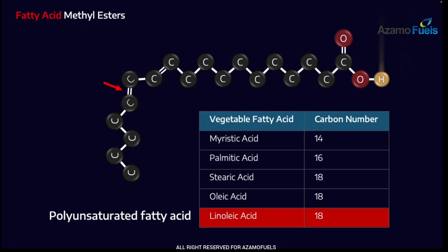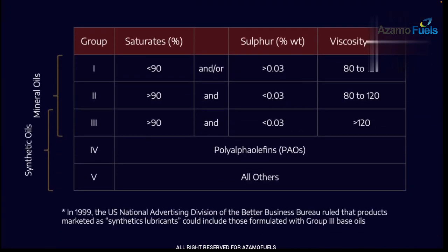Now, what's important about saturation? Why are double bonds undesirable? Well, if you remember back to our API base oil groups for lubricants, one of the things that defines group 1, 2, and 3 mineral oils is the degree of saturation.